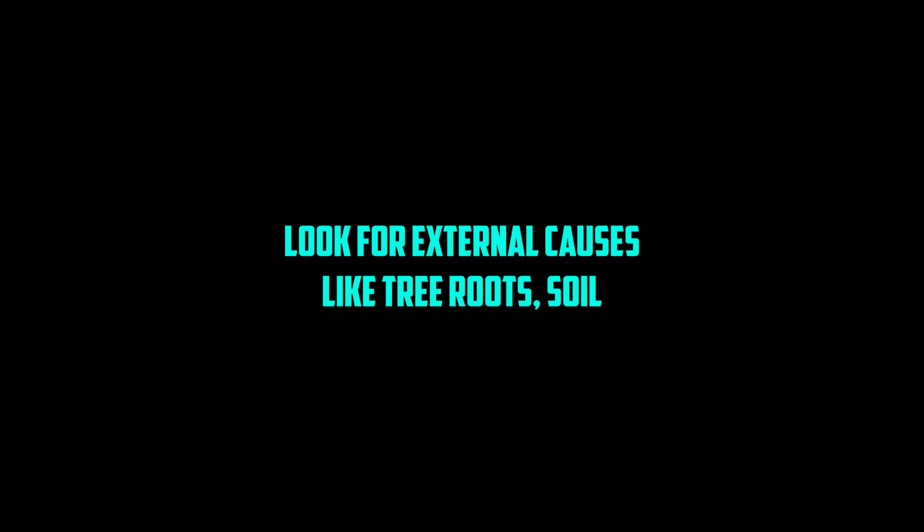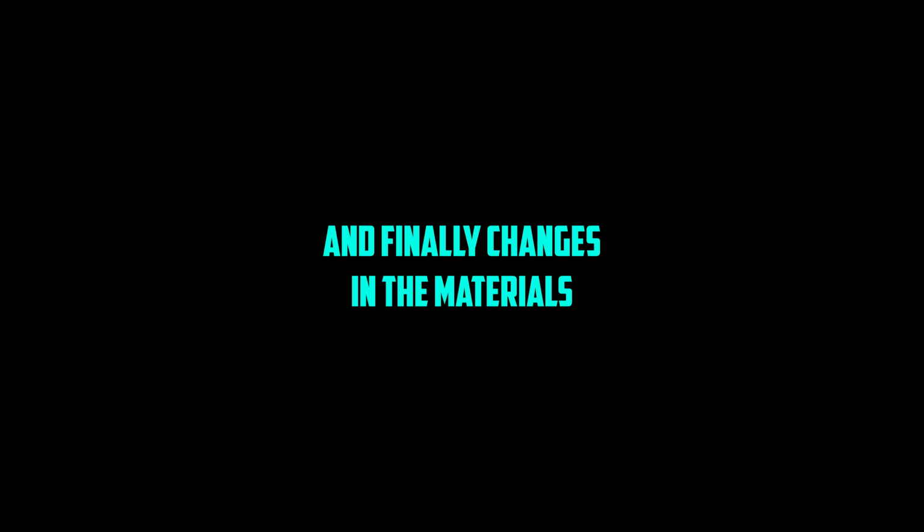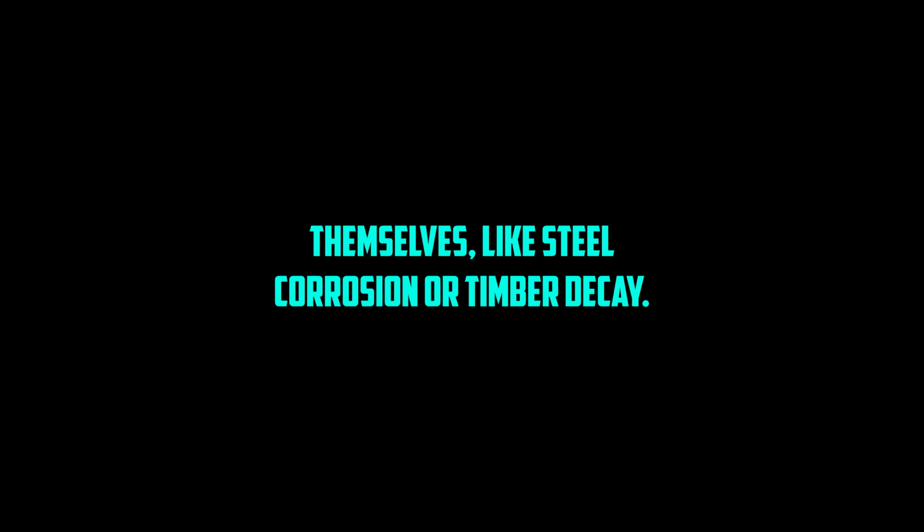It sounds complicated. It can be. The handbook suggests a systematic check. Look for external causes like tree roots, soil movement. Consider climate effects, expansion and contraction, moisture problems, leaks, damp-proof course issues, vibration from traffic or construction, and finally, changes in the materials themselves, like steel corrosion or timber decay.